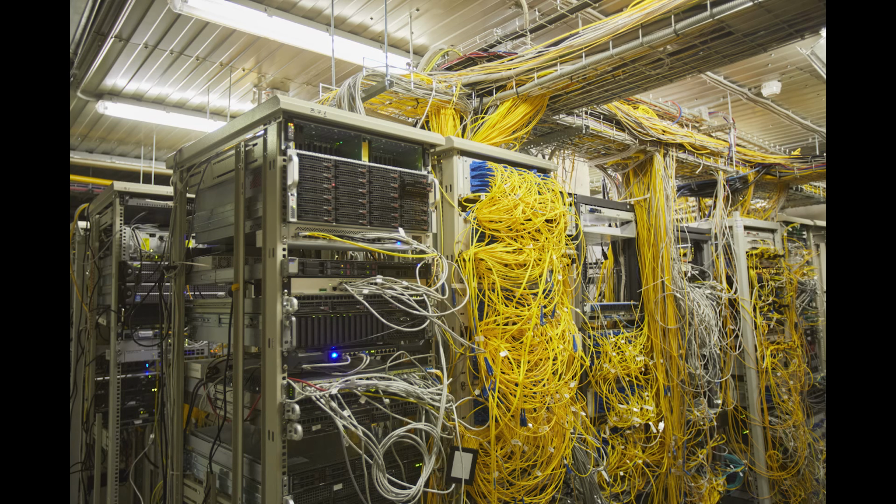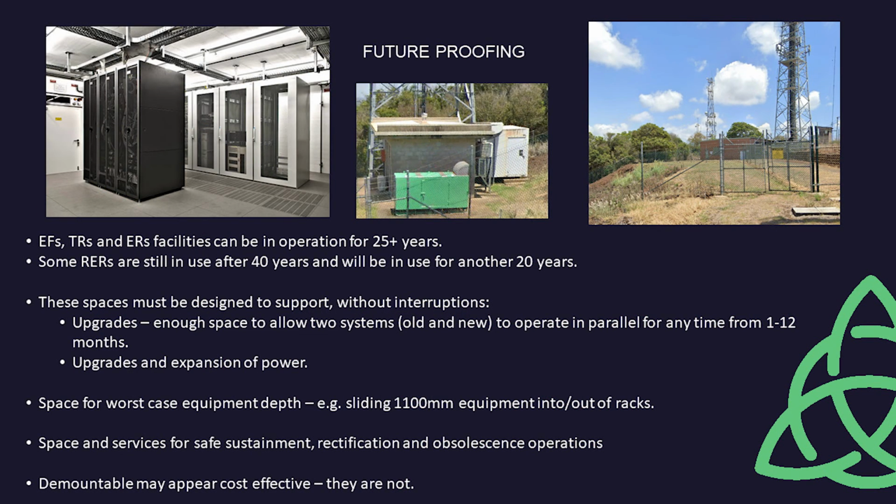Let's circle around to the power requirements within a room. The equipment rooms and dedicated entrance facilities require separate supply and a separate power distribution subboard within the room for the equipment. If deemed necessary, the room should be fed from essential power if available. Provide 2 separate phases, one for general light and power distribution. Provide convenience power sockets. These are used to power test equipment, laptops, and the like. This prevents maintenance staff from plugging test equipment into equipment rack power socket outlets. These convenience power sockets should be located at 1,000 mm above the floor level and evenly distributed around the room.